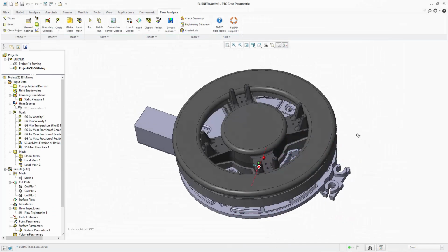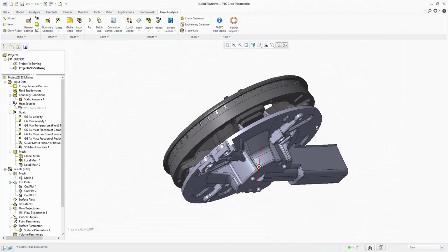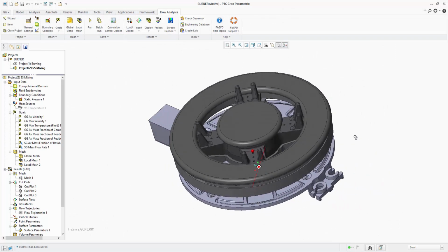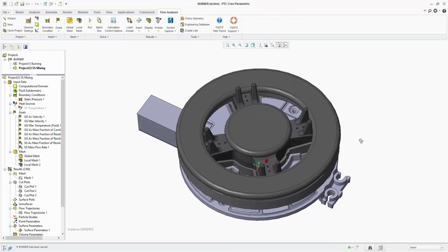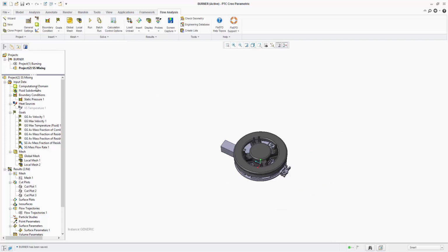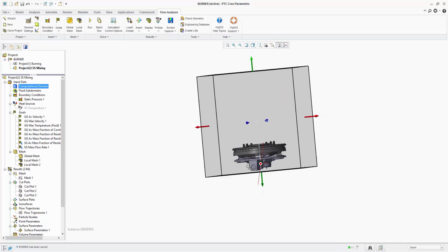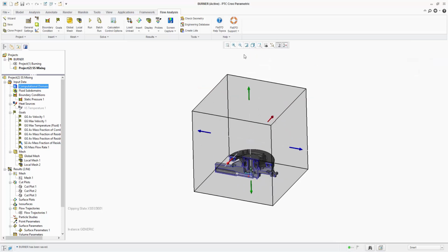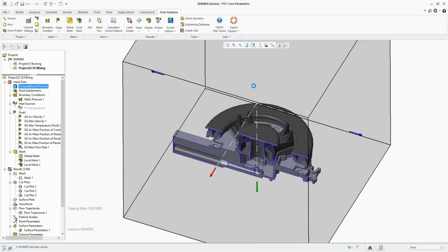For this demonstration of the combustion capabilities of FLOEFD, we'll be using a domestic burner ring which uses methane for fuel. There is an inner and outer ring and an additional igniter part which we'll cover later. This analysis will be performed in two steps: the cold mixing in steady state and the transient burning phase. The computational domain size for the mixing analysis can be seen here.